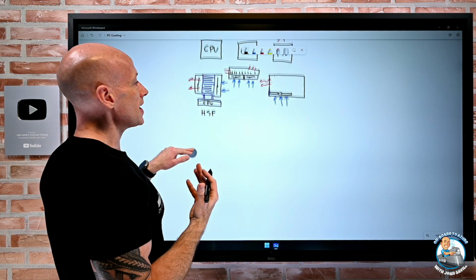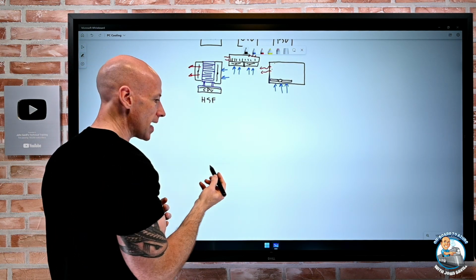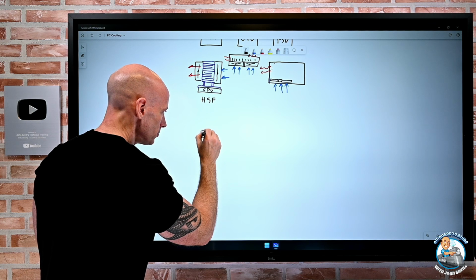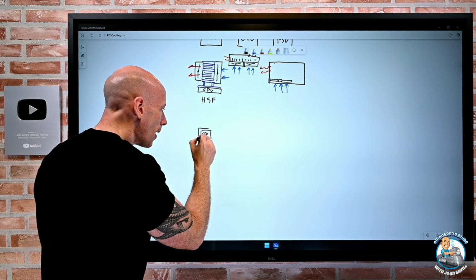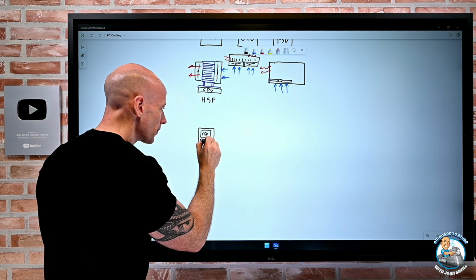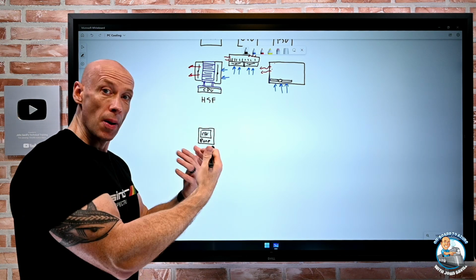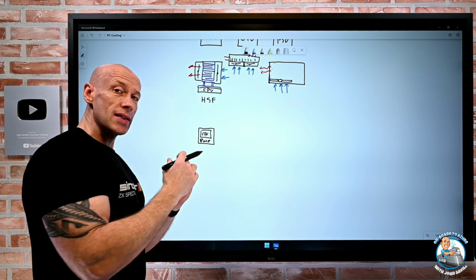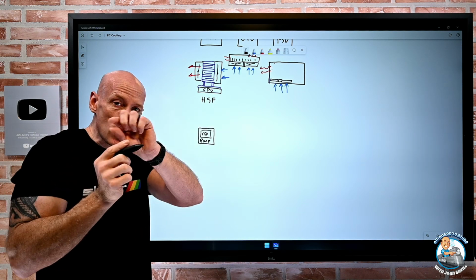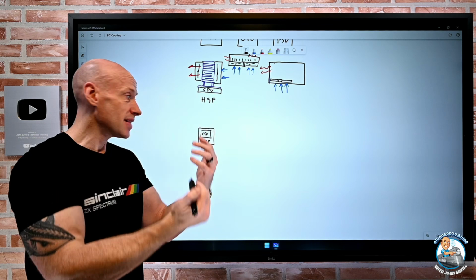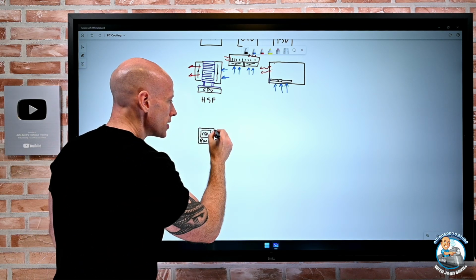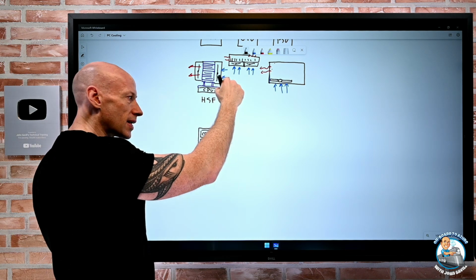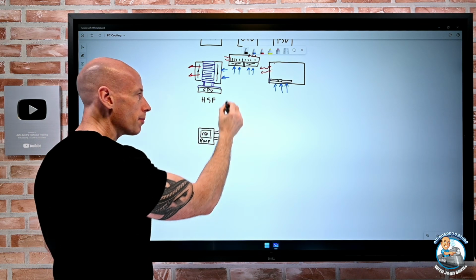Another option you'll commonly see now, and I'm going to flip orientation again, is an all-in-one. So with an all-in-one, yes, I've got my CPU again, but then what happens is you have a pump that basically sits on top of it with, again, a big copper base, so it's drawing the heat with some thermal paste. This has thermal paste on it as well. And I can orientate, it's going to have a radiator, which is really lots of fins with water pipes going through it, and then fans again. And I can orientate it one of two ways. So maybe it's going to have two pipes. One is going to have cold liquid coming back to it. One is going to, after it's been on here, it warms up and the heat goes away.